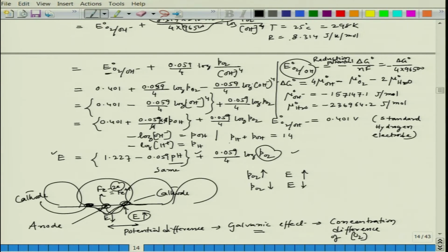So, finally, this will be like this. This corrosion will be unified over the entire segment of that particular surface. So, it will be uniform over the sections, though in an individual droplet we have a localized mode because of this concentration effect. So, what I said is that in most cases of uniform corrosion, you would see that it will end up in galvanic mode. Okay? We will see a lot more examples.